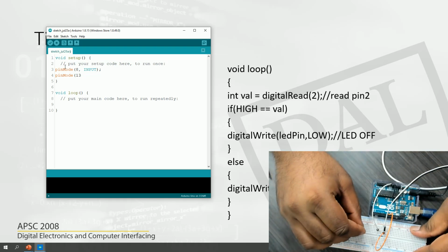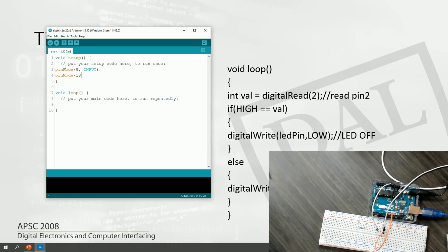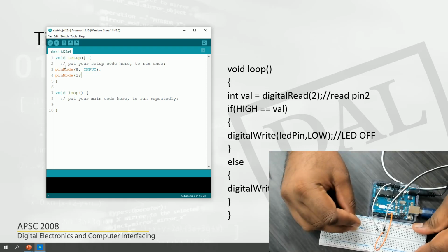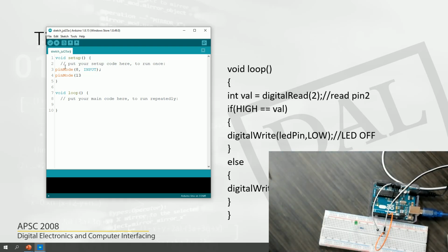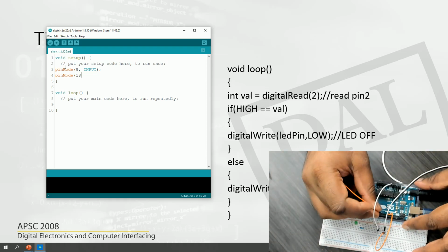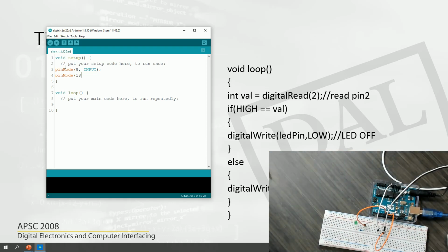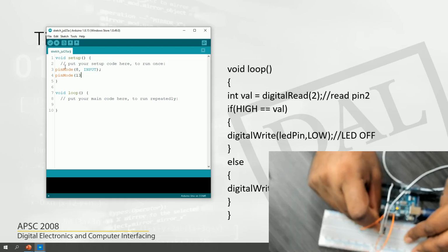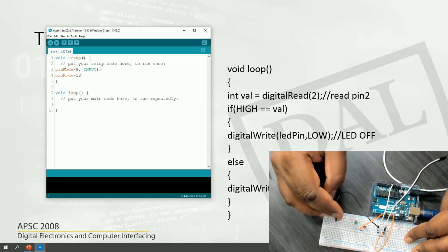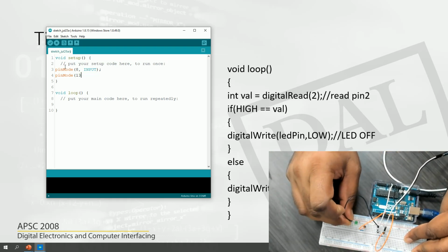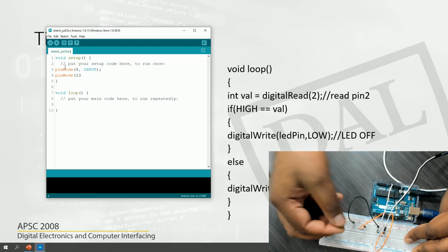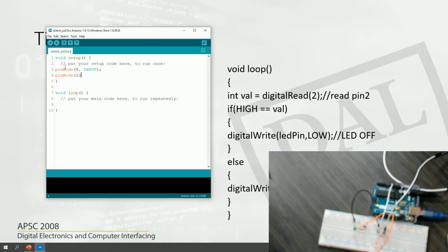So I'm going to just have another output circuit and wire them. I will use pin 7 for this, so I will do pin 7 as an output, and connect it to that. Take another wire and connect it to ground. I can probably take this ground and apply it here. I want to make sure of the orientation of the LED.